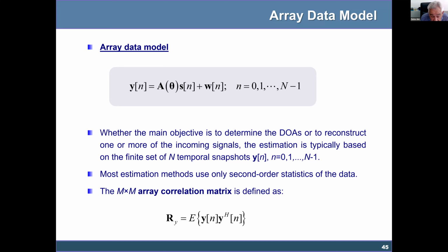If it is passive, typically we do spectral analysis to understand the properties of the source and classify the source. If we are in an active sensing scenario, we do matched filtering and we estimate the range and the Doppler frequency of the target, and so on.